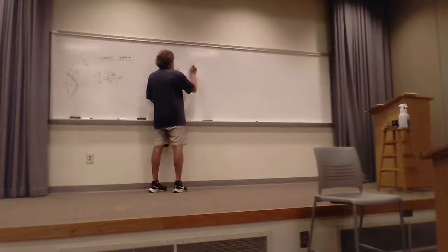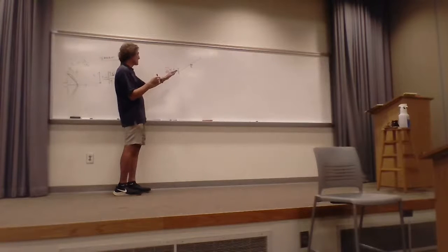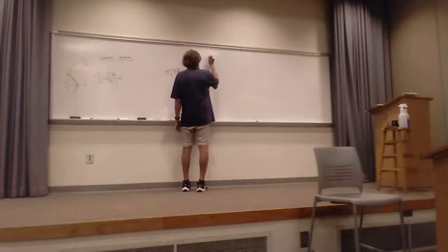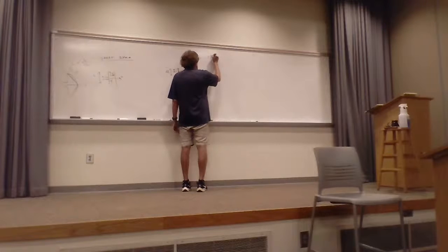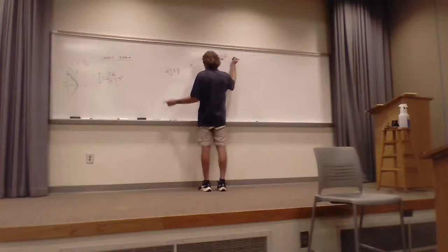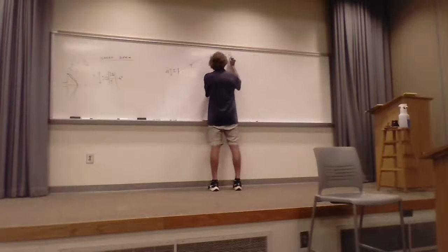So if I'm a distance R away from that little chunk of wire, doesn't matter, has nothing to do with angle or anything like that, just distance R away, there'll be a differential magnetic vector potential dA equal to mu0 over 4 pi times I, the actual I times the dl vector. It has a vector sense, or the direction, same thing as I dl, and it will be divided by the magnitude of R. It will be times e to the minus j beta r.